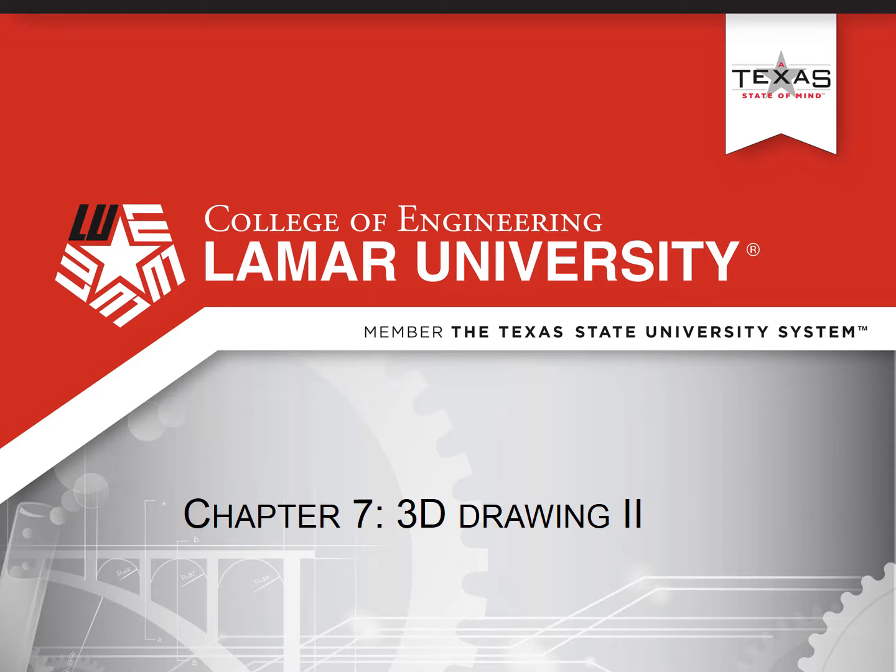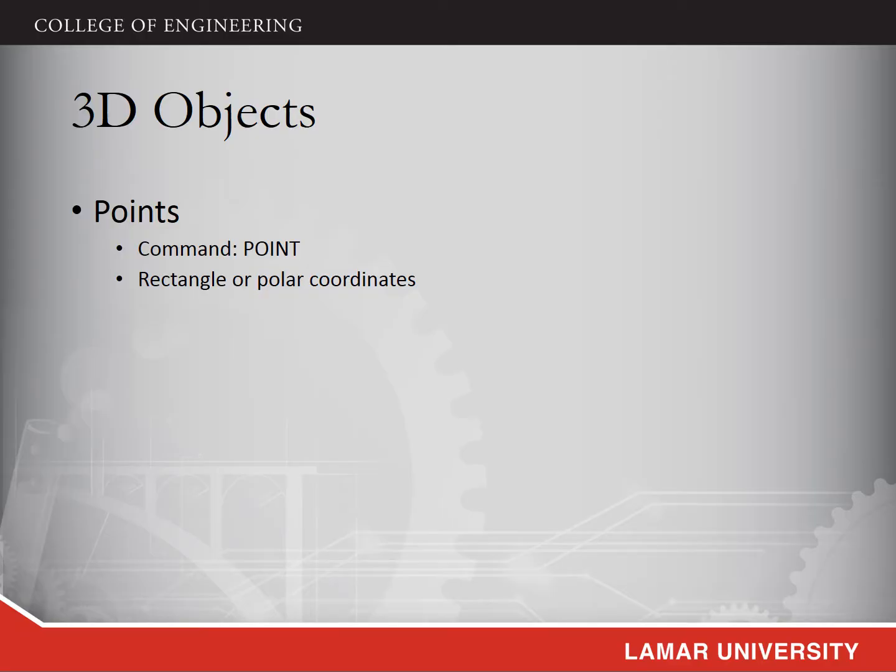In this lecture, we'll go through the commands to draw three-dimensional objects in AutoCAD, such as points, lines, boxes, cylinders, cones, and so on. In three-dimensional space, the generation of points is very similar to two-dimensional drawings. You can still call the command point to generate multiple points under the 3D environment. And if you want to change the type and size of the points, you can also call the command ptype. These are exactly the same as the two-dimensional drawing.